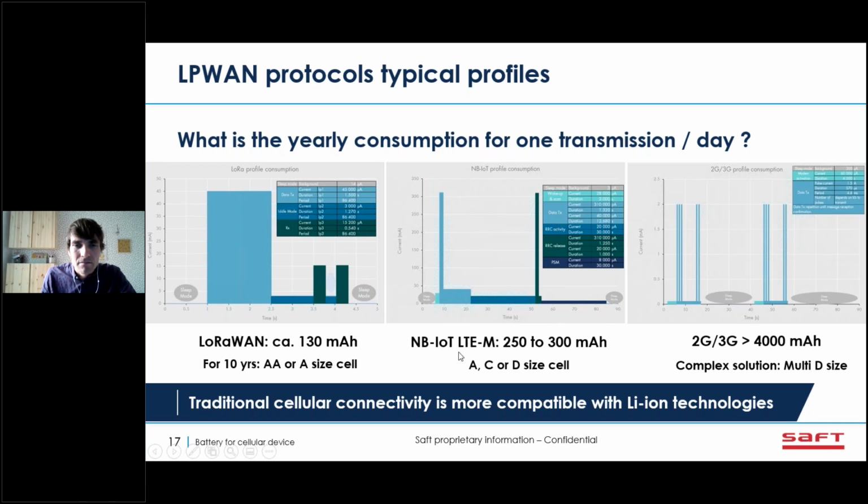But for LTE Cat-M modules, you can have peak current up to 500 milliamp, for example. Yeah, and even if I see the average consumption of the transmission, it will be closer to 120, 130 milliamp. But you can have peak current. Yeah. And I think this also states that under PSM you have a quite significantly lower current of 8 milliampere. Yeah, 8 milliampere during 30 seconds.